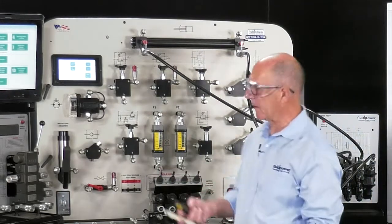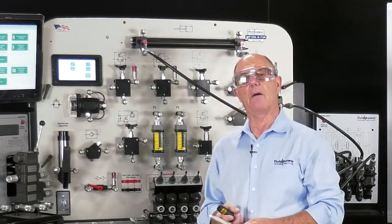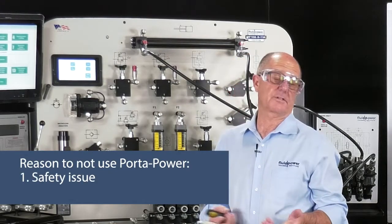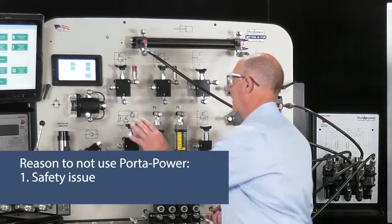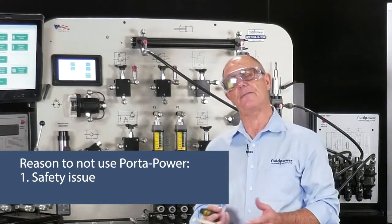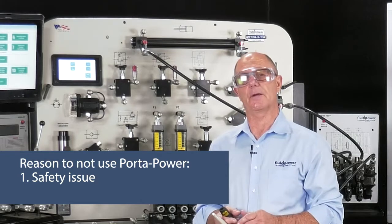Now, most people will look at that and say, well, no, that's a Porta-Power. Well, there's two reasons why you don't want to use a Porta-Power. Number one, it's a safety issue. The relief valve in the Microleak test pump is set at 3,000 psi, and the relief valve in a Porta-Power is set at 10,000 psi.